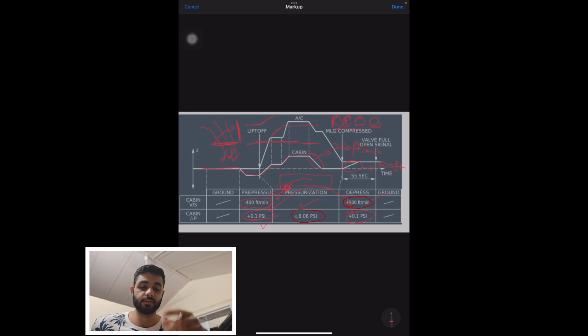It finds this valve is opened out. It says, okay, atmosphere is out there, let's go out there. Okay, so it damages this duct because you're ramming air into it and air is coming out from that side. So to prevent any sudden depressurization of the aircraft, it won't open if there is delta P greater than 1 psi.